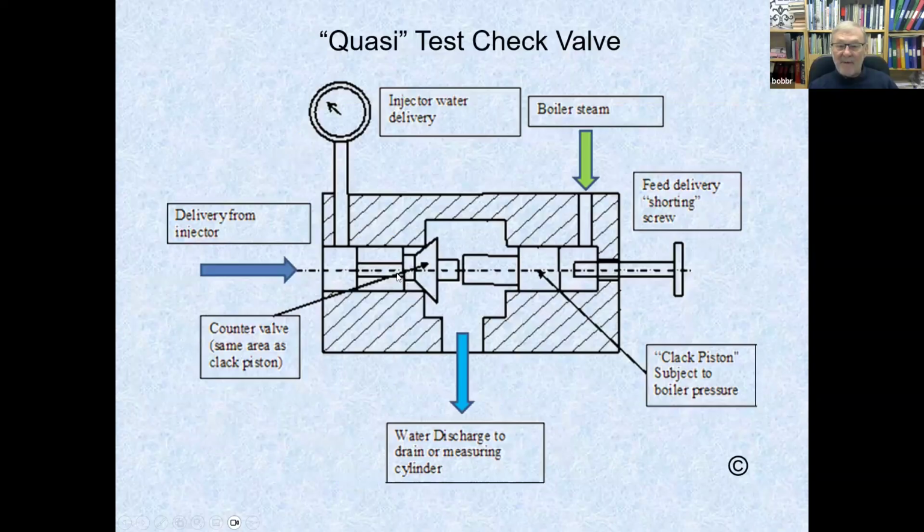So just to explain the valve a bit more, the area between there and there is exactly the same as there and there. So the pressure on this end equals the pressure on that end, and that gauge reads it off. There's a gland in there, of course, when you close that, that screws this hard up against that and stops the flow into the atmosphere, and you pressurize the delivery, and you'll see that gauge go right the way round. And that is the margin, the reserve that I told you about, very often twice the delivery pressure.